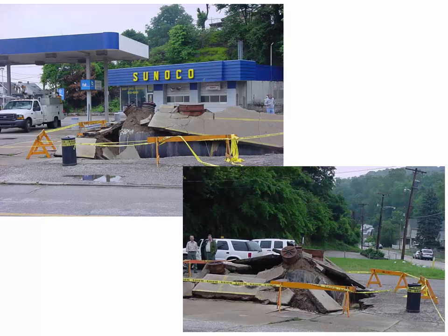Well, then the buoyant forces might exceed the tiny little weight of the tank, and then it can come crashing through the concrete unexpectedly, like an emerging submarine out of the soil. So that's what happened here. Actually, this is an old filling station in Charleston that was out of business. The water table rose, and the buoyant forces pushed that fuel tank up out of the ground.